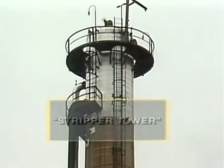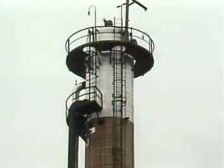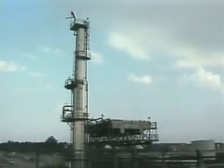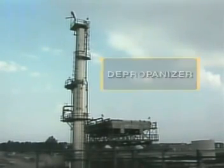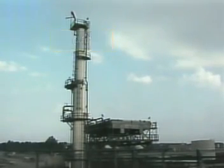Another type of tower is called a stripper tower, because it strips lighter components out of the products. However, unlike most other distillation systems, a typical stripper tower system does not condense the overhead product into a liquid. Instead, the overhead product remains as a vapor and is sent for further processing. Some towers are named according to the chemical product that is being separated. For example, a tower that separates propane and lighter components from a feed can be called a depropanizer. The overhead product from a depropanizer contains mostly propane and some lighter components. Components that are heavier than propane end up in the bottoms product.